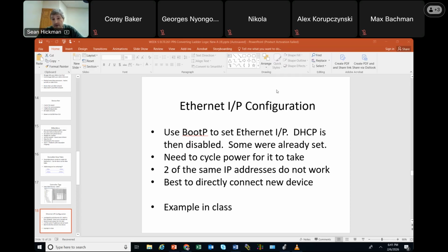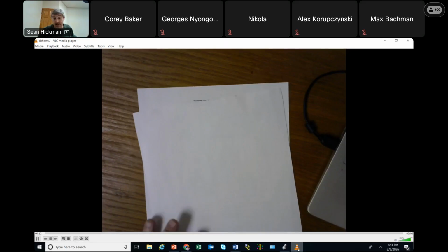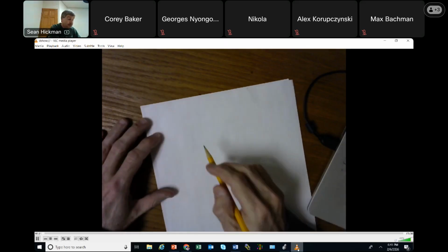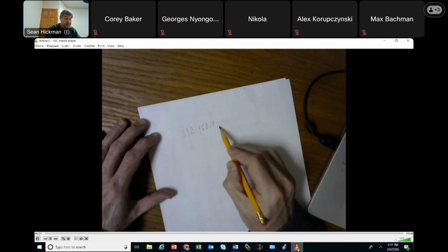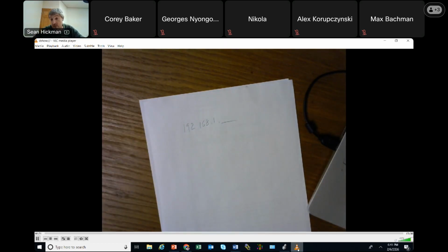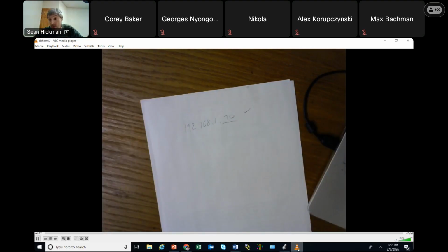And so the reason, I want you to be sure you understand this, so you can move forward in life and be successful in life. If you're going to be successful in life, you got to understand this. Allen Bradley equipment, when you buy it, if it's going to come from the factory like that, a lot of times it's going to be on this network right here, okay? And if we were to click the thumb wheel to 70 on that remote Ethernet adapter, it would be 70. That would be my remote Ethernet adapter.